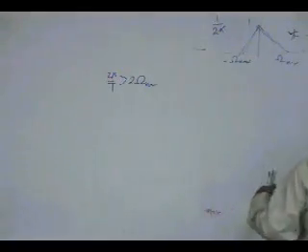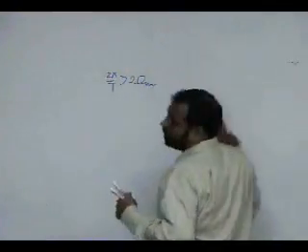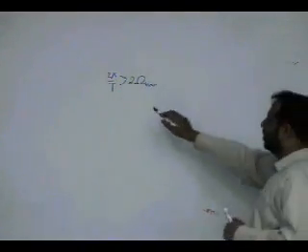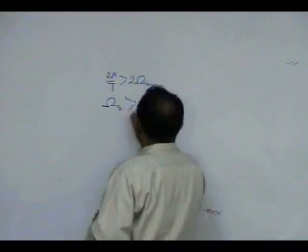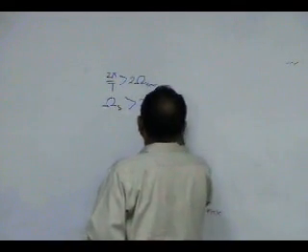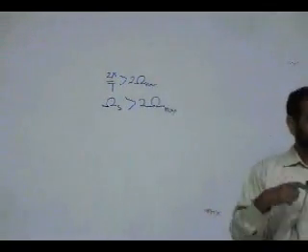And this is what I explained last time while teaching sampling. I said, in time domain you can appreciate it more, but in frequency domain this is the rule, that omega s must be greater than twice the highest frequency. If you don't obey this, the signal will alias.